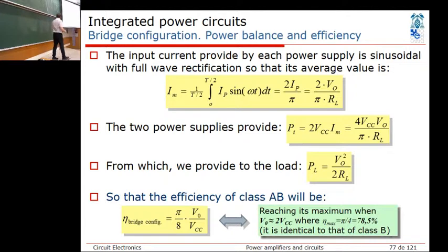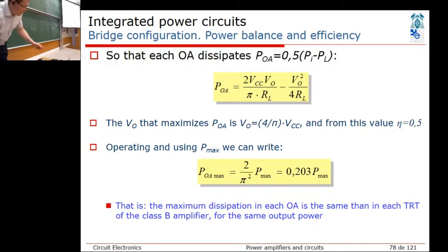So if you are basically using the bridge amplifier design, it doesn't do anything for the efficiency. It just makes the requirement for the power source voltage lower. You get more power out of the design with the lower voltage. That's what it does. Yeah, that's more details.